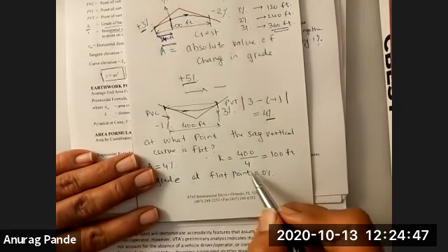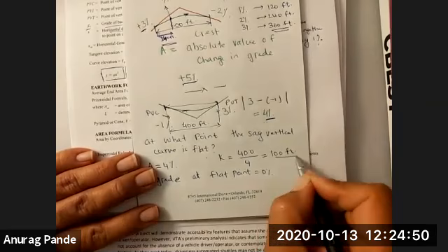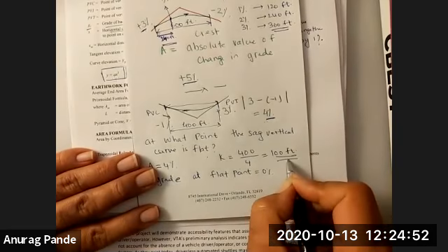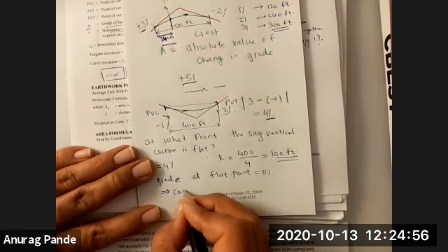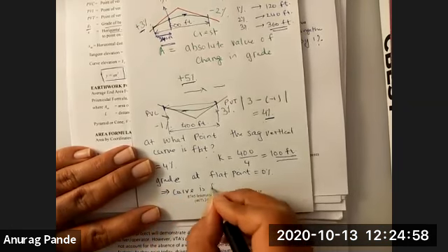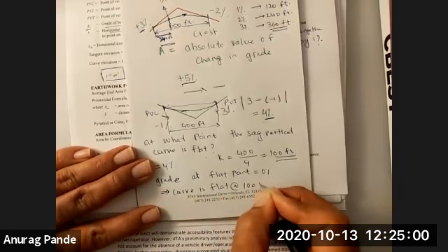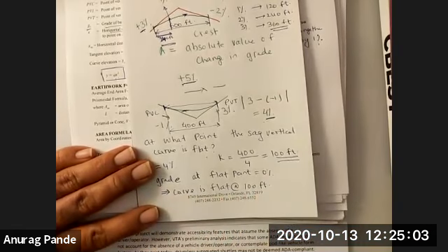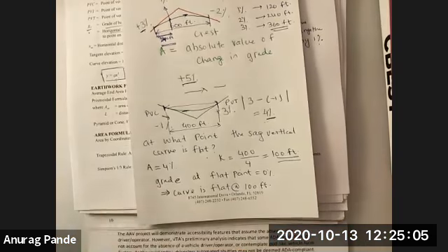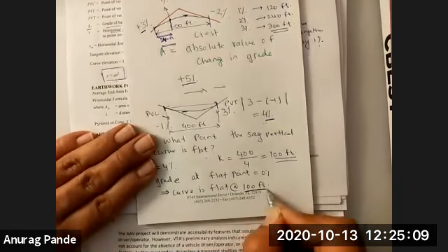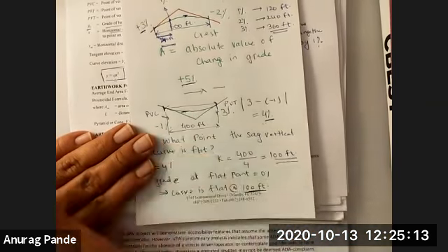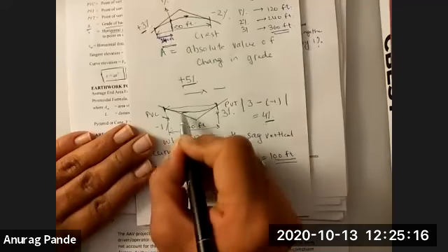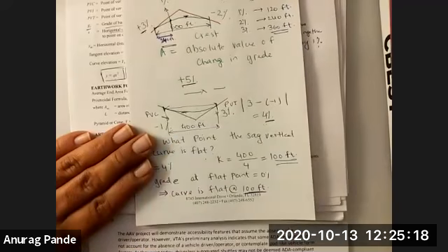How much length do you require to make a 1% change? It's 100 feet, because that's the definition of K value, right? So that means the curve is flat at 100 feet. One station away, because remember, I told you stationing is measured in 100 feet. So that's another concept you could relate to it. At one station away from PVC, your curve is flat.